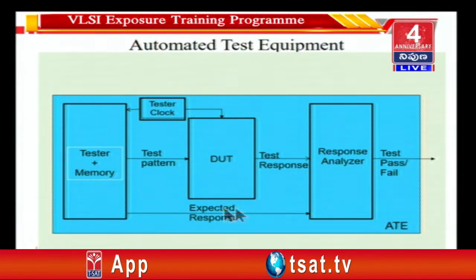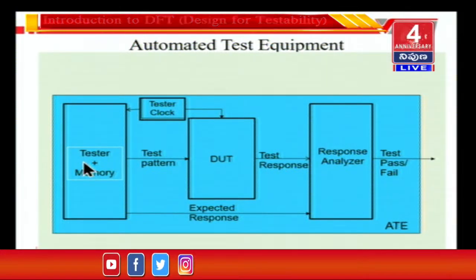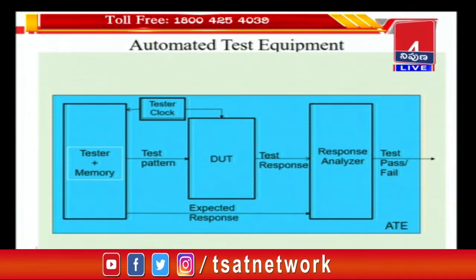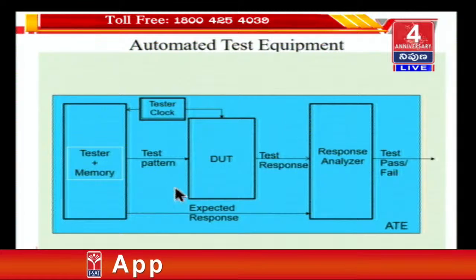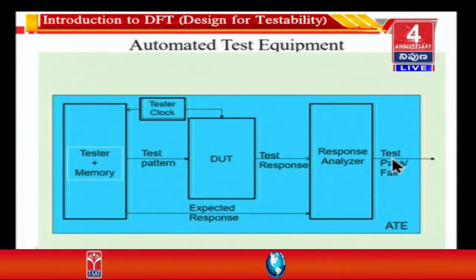The expected response is also fed to what is known as the response analyzer, which is a part of the tester. Do not think that the response analyzer is a different kind of equipment. It is a part of the tester, and when it compares the expected response with the obtained response, it decides whether that particular test has passed or failed.